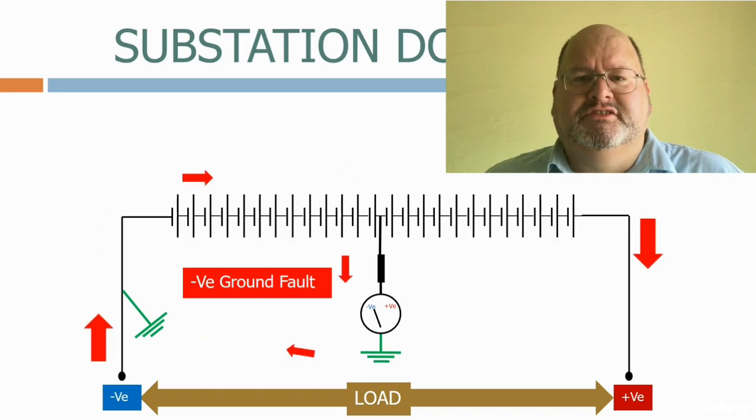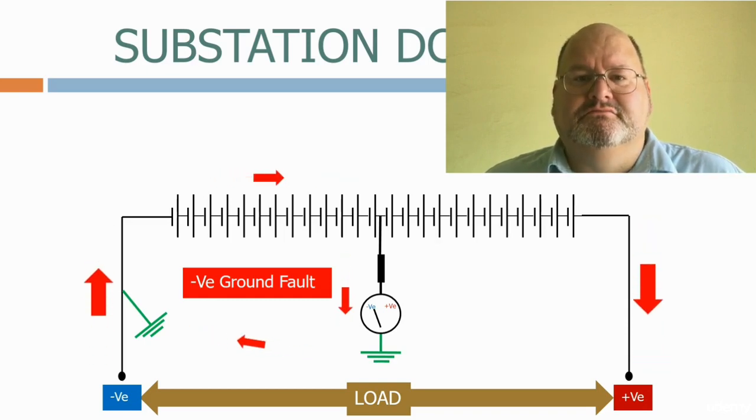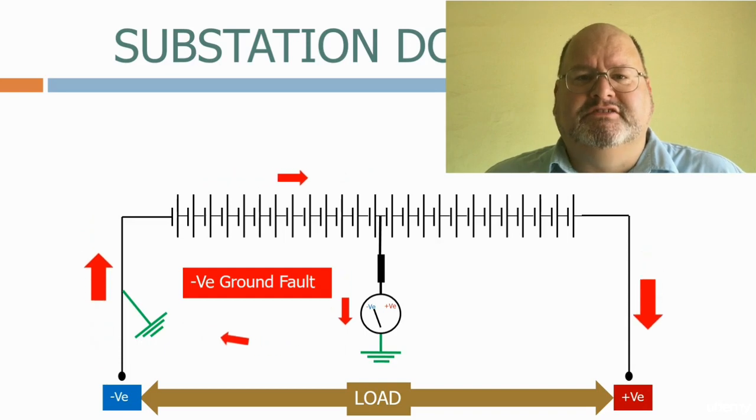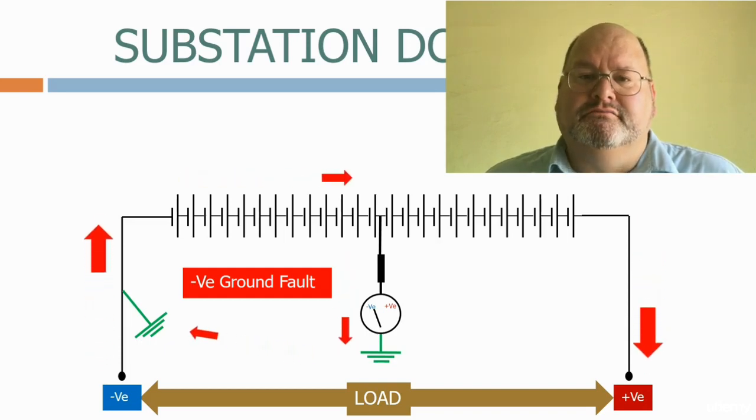It is quite common for older substations to have a number of minor battery earth fault alarms caused by the insulation on the cables and equipment failing as they age. These will be very difficult to trace, and many may be left in place until the DC system is fully overhauled.